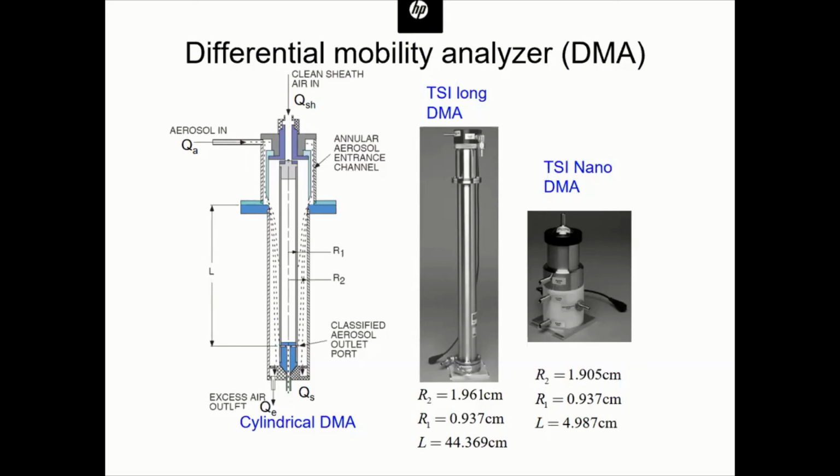So basically during the entire day, it's expected that we can get enough mass to let us know the mass distribution or the size distribution. But during the whole day, a lot of things can happen, right? It might be very clean in the morning and in the evening, but very polluted at noontime. So basically, the cascade impactor can't give you enough time resolution, while these instruments can give you real-time measurements, right? So it can give you the size distributions after each minute, right? So you can get a lot more information regarding the dynamics, right?